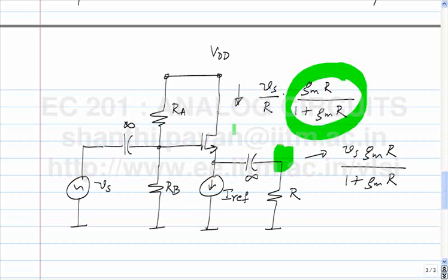And we saw that when you have a negative feedback system, the closed loop performance is independent of the forward amplifier as long as the gain of the forward amplifier is sufficiently large. If the Gm is sufficiently large, it basically means that the transistor doesn't tolerate any nonsense. The moment the incremental source voltage is even slightly different from the incremental gate voltage, it goes and kicks the resistor so hard that the output voltage better become equal to the input voltage.